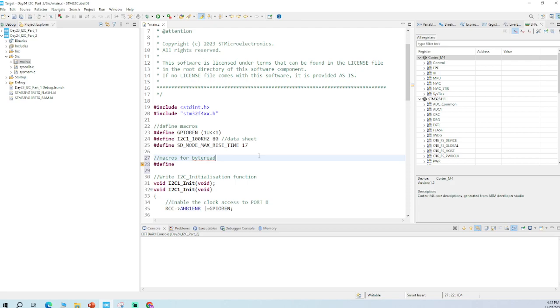first is for the control register one. Has defined, so you need to start with the start bit, control register 1, control register 1 start condition, and as we learned from the theory, it's the 8th bit. You need to enable that.